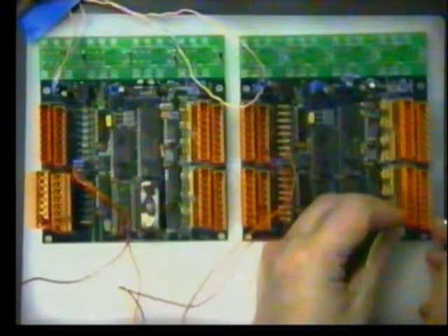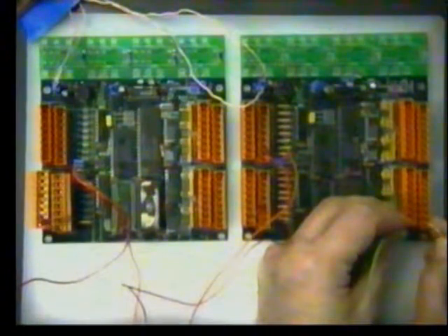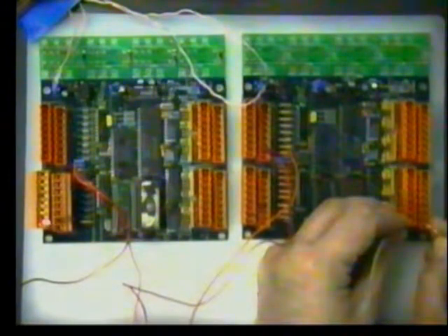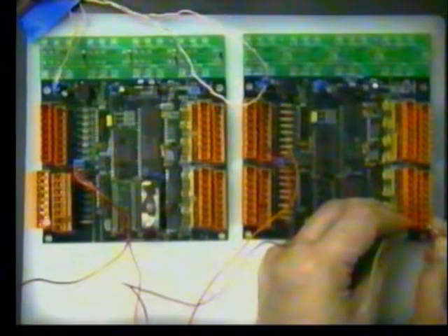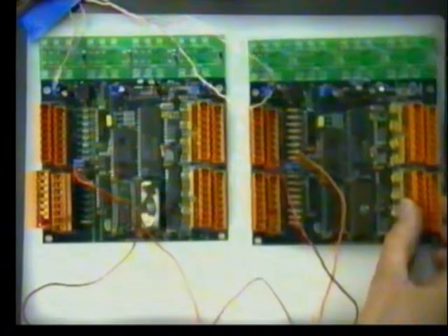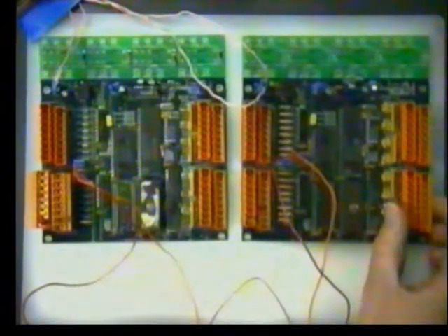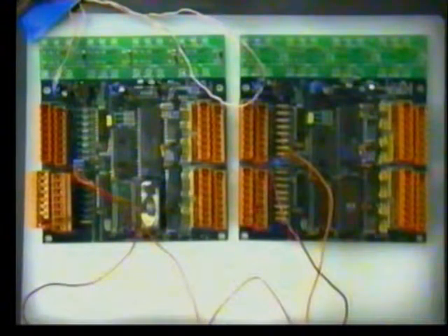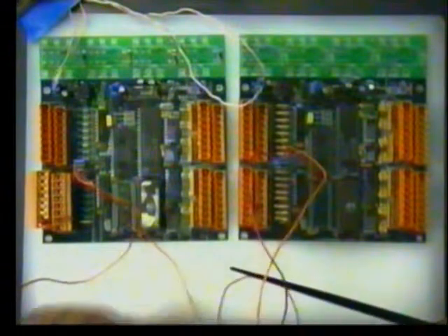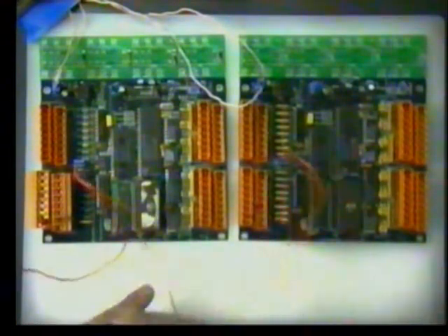So if I was to close, for example, a switch by simply shorting things out, hopefully you can see the lights are coming on. Now how is that achieved? Because these are two totally independent boards. It's done via this two-wire CAN bus network. What I've done is I've defined a CAN bus channel where this is transmitting the channel, and what it's transmitting is the status of these switches. So I've got these switches being broadcast on a regular basis into the CAN bus network, which is just two flimsy little wires. That's all they are.